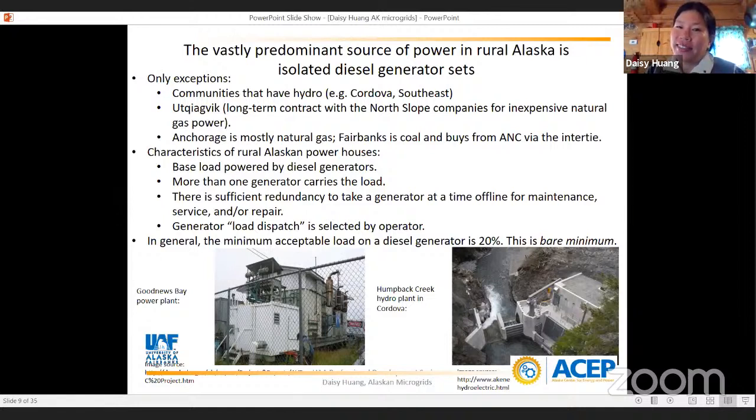So the other advantage of diesel, which I probably should have put as a bullet point, is unlike any renewable, with diesel, you can control exactly how much you make. Like it can follow the load. At night when everyone's asleep, the load demand is very low. And in the morning when we wake up, start making coffee, toasting bread, the demand goes up, right? So in the course of a day, the demand on the grid goes up and down. And diesel is very nimble. It's a spinning thing, spin faster, spin slower, make more or less power. You can't do that with solar and wind. Like they don't follow what you want them to do. And so you always have to have some diesel. Like it's really hard to be 100% renewable.